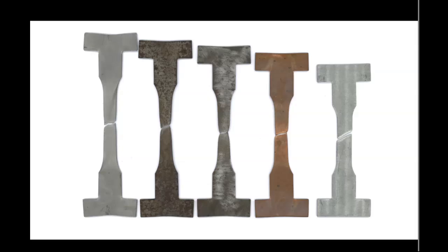Then option B, the maximum stress attained prior to necking. Stress localization. No, this is incorrect. Option C, the stress at which permanent deformation occurs after fracture initiation. Also not correct. Permanent deformation indeed starts at the yield point, but the caveat here is after fracture initiation. Yield is not where the sample fractures.